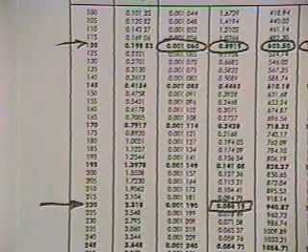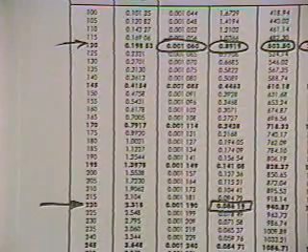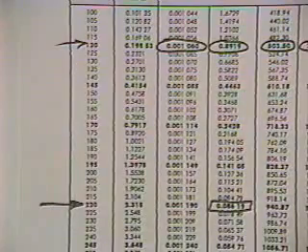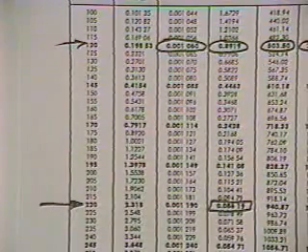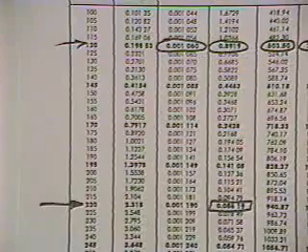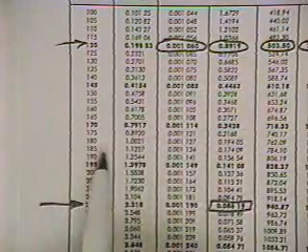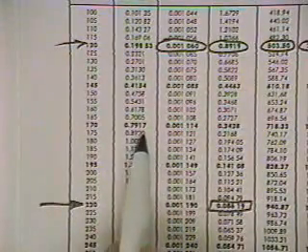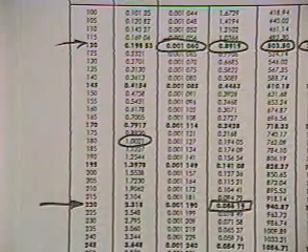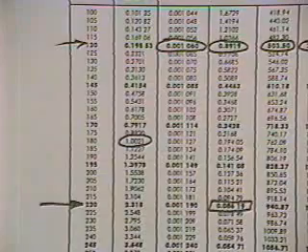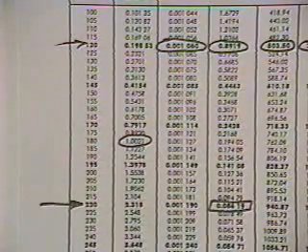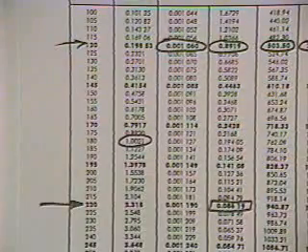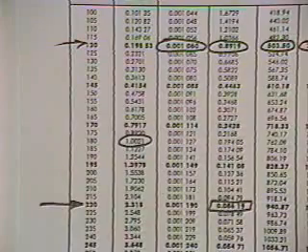But in our particular case here, this is set up so that it's in even increments of temperature. So sometimes you won't be lucky enough to find an exact equivalent on pressure, so you'll have to do some interpolation. But in this particular point, if we come down here to 1 megapascal, we have a tabular value that's 1.0021 megapascals, and so that's plenty close enough for these most nearly correct sort of answers that you get on the FE exam.